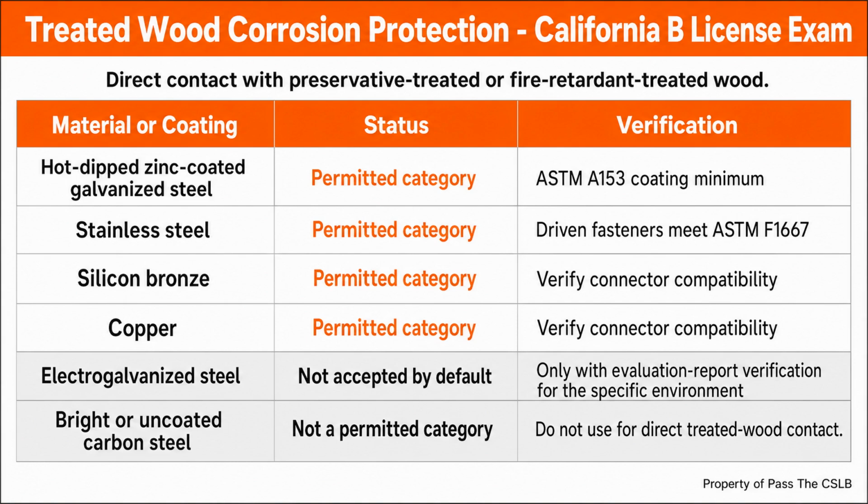The Division of the State Architect interpretation identified in the research report states that prefabricated wood connectors must not be field bent, cut, or altered unless the manufacturer's instructions and the corresponding evaluation report specifically permit that modification. The important distinction is between fitting the framing to the approved connector detail and reshaping the connector to fit an improvised condition. If a pipe blocking conflict, skewed member, or misplaced opening interferes with the hardware, hammering a flange flat is not a design solution.